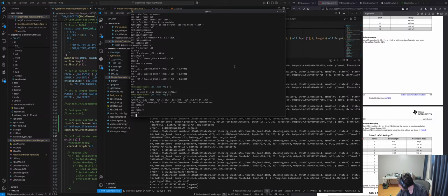Hold on. Let me just double check this again. I might have just had a bad contact because I thought this battery was at a higher voltage. But that was an open circuit voltage. Oh, I can't read. So yeah, it says if I squeeze the probes in here real nice and good.